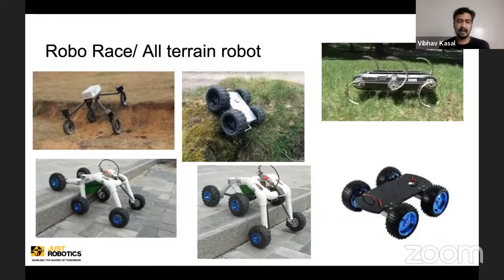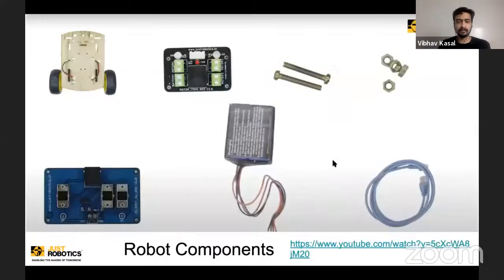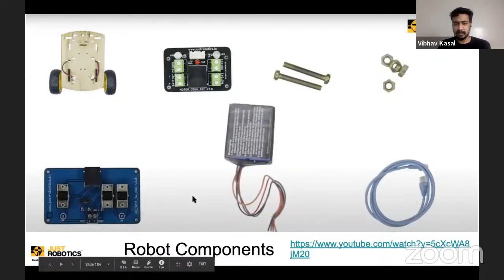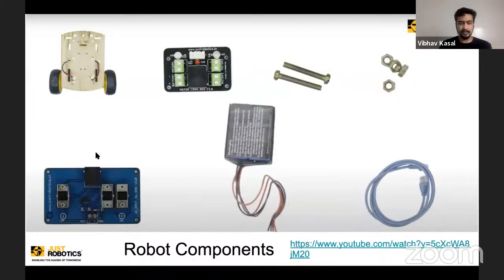So you will still have 6 wires coming through the robot to the remote. For that, what we use is an Ethernet jack, which has more than 6 wires. There are RJ45, RJ9, based on the number of wires that go in. So we use this multi-thread cable, so that you can simply plug and it starts working.